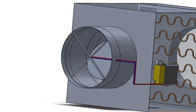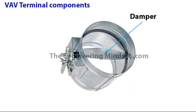You can find the differential pressure across the device, and if you average that for the size of the duct and calibrate it a bit, then you can calculate the flow rate of air entering into that box and zone. Let's just show you what some of the components look like.